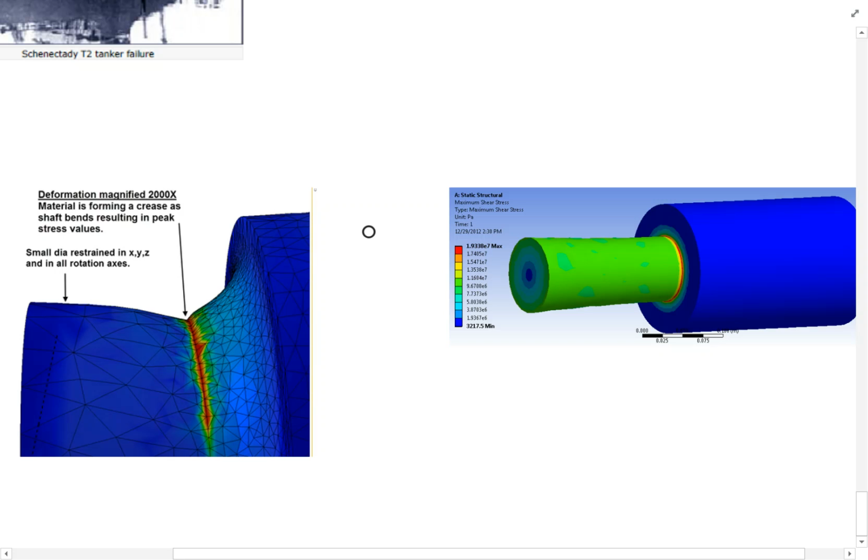If my meshing, and you can sort of see that really well here. If you look, can you guys see that out there? Can you pick out that meshing? See how big the meshing is here? What you do, to overcome the computational problems, is you mesh fairly large in areas that don't have a rapid change in cross-section. Okay?